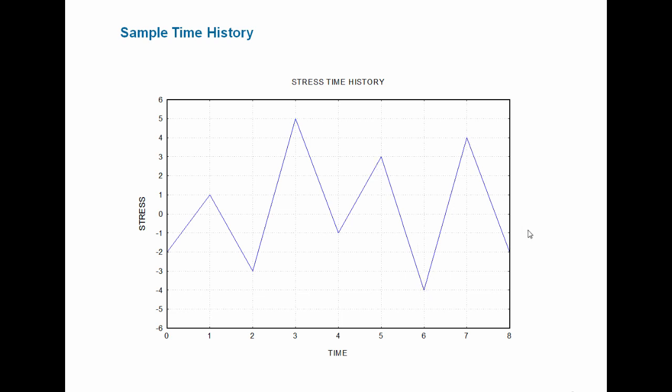And if this was sine vibration, sure, that would work. That would work just fine. But for the case of random vibration, where we have all sorts of localized peaks and valleys, it really becomes kind of nebulous as to how to go about doing that rainflow counting.